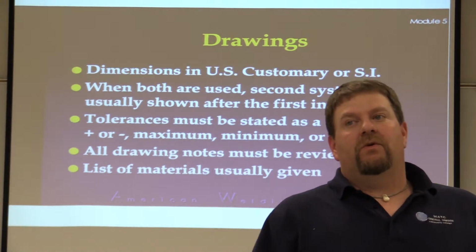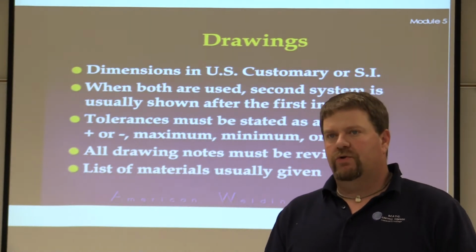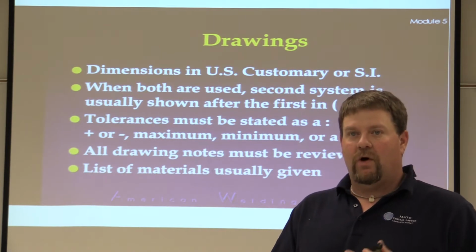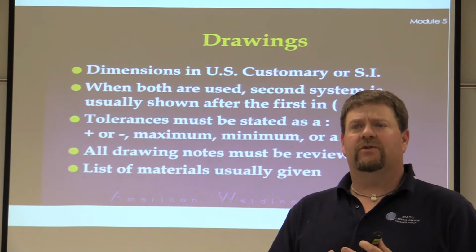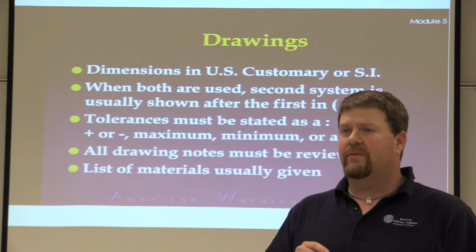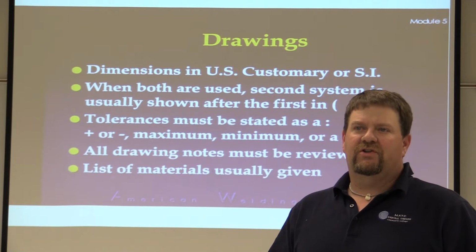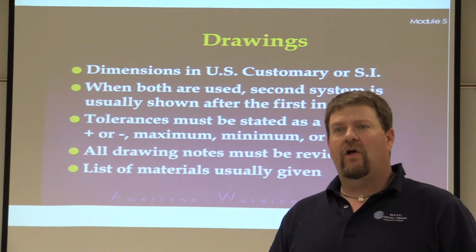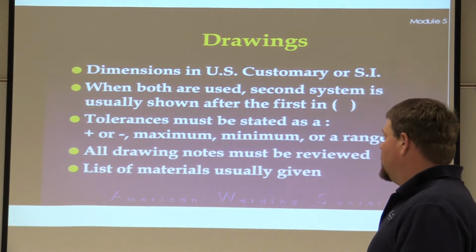Before. Usually when you're going to bid a job or you come on a job, the very beginning, the most crucial thing you can do is study all the documentation. Number one, what's the material prep? How do you isolate your materials? What's the code for it? Do we need to worry about purchase orders? Is it there? Do we have MTRs on everything? Absolutely. What's the hold points? What's the requirements for inspection? Does every part need to have a visual inspection? Does every layer need to have a visual inspection? You have to know all that before you start, okay? And then make sure you adhere to it all the way through that as well.